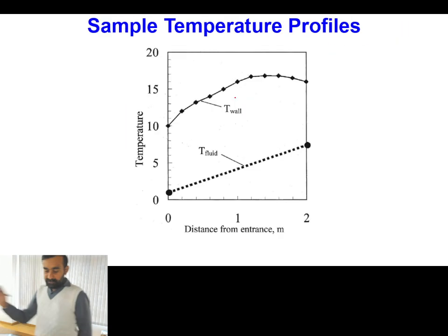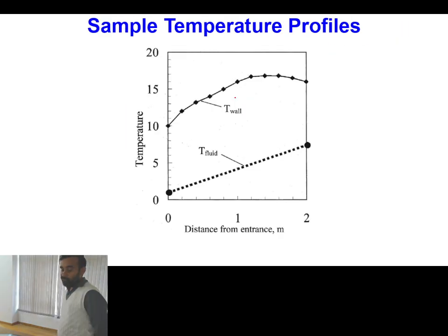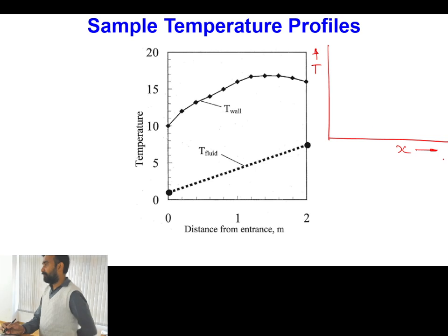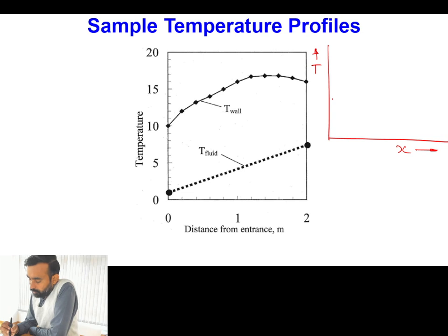Now after doing this, here we have to also understand how to install our thermocouples, or at what locations we need to install thermocouples. So typically we know from understanding of convection heat transfer, if I consider the x, like distance along the length of the pipe, and temperature, then in the developing region my temperature of wall varies something like this, and after the flow is fully developed, for constant heat flux condition, it actually varies in a linear manner.